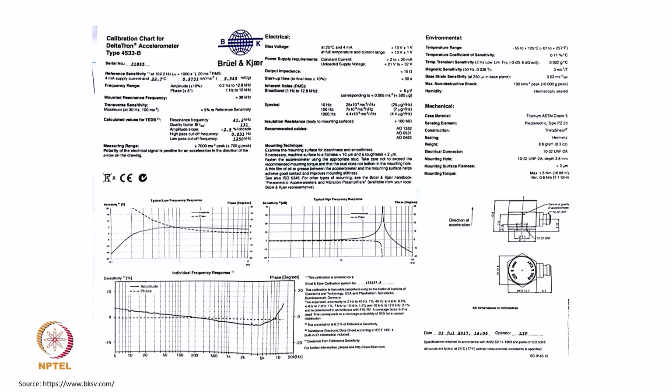Okay. And I am going to now pop up a calibration sheet of one of the accelerometers here, and you can notice its frequency response characteristic. You can see that the response or this sensitivity is having a linear behavior, and that accelerometer has a resonance somewhere here. And what is that value? This is 10 kilohertz, this is 20 and 30 and almost slightly less than 40 kilohertz.